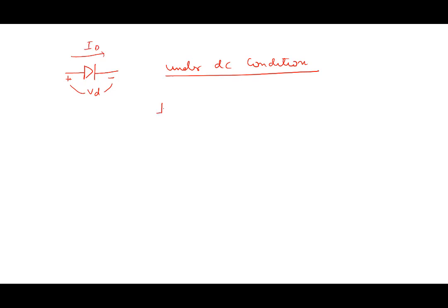So my diode equation is ID equal to IS times e to the power VD by NVT minus 1. It can be more complicated than this. Remember, this is also a model. I'm building a model, and there can be more complicated models also. But for us, this could be a starting point. A diode is represented by this exponential characteristic.